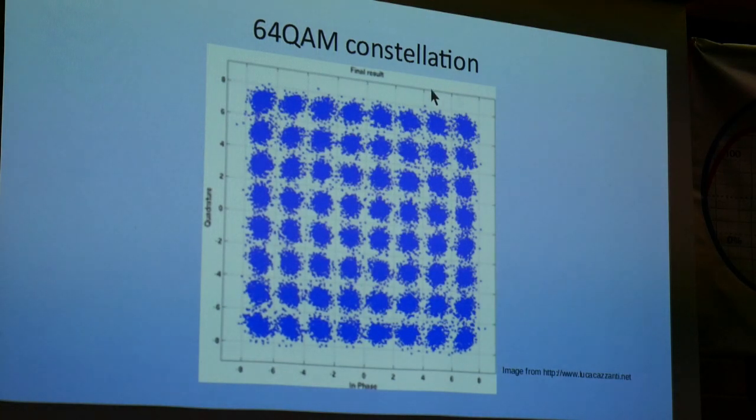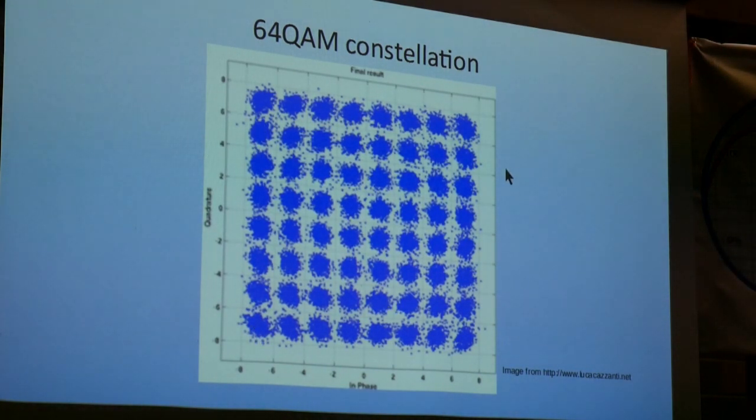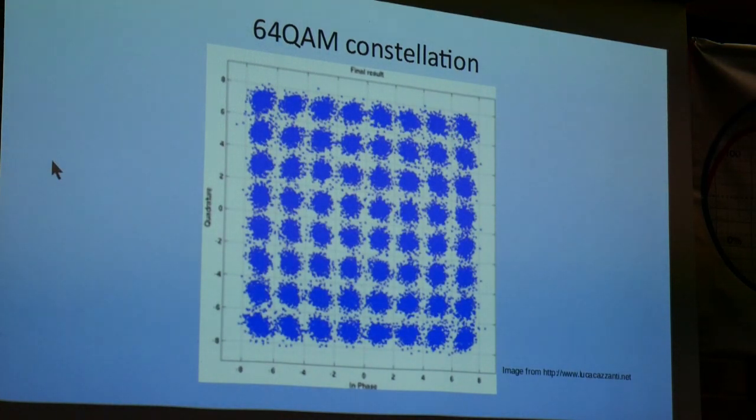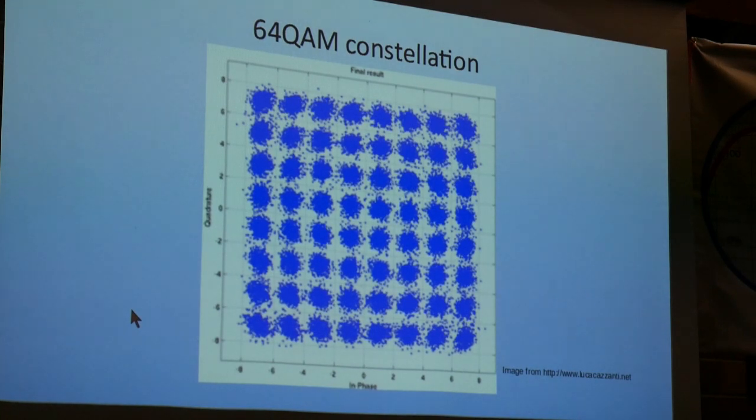In each of these directions, it represents amplitude modulation. Whereas with QPSK you'd have only had 4 points here, which is 2 bits per symbol, all you've done is add extra points in each direction, in X and Y. These are 90 degrees apart, 2 axes, both of which are amplitude modulated. So that's different to what I said last time about the way DVB-S works, which is phase modulation. This is exclusively amplitude modulation.